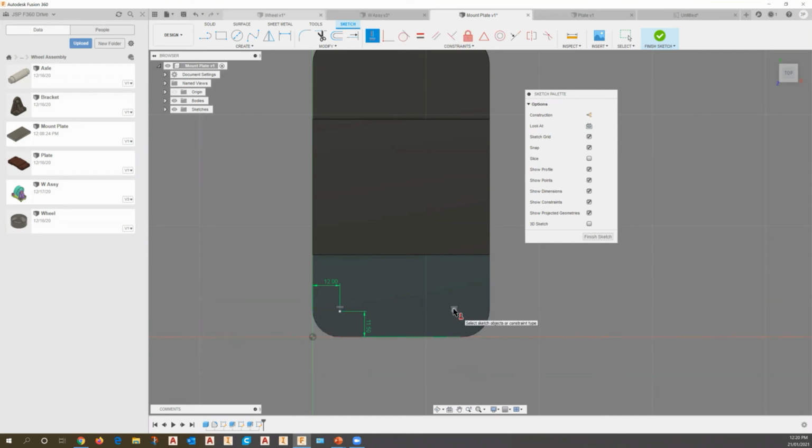So now I know that this one here is 11.5 millimeters off the base because I've used a horizontal constraint to align these 2 points horizontally. Now, the other thing, when I'm creating a dimension, if I want a dimension to be equal to another dimension, effectively I can pick this other dimension and apply that one to the distance here.